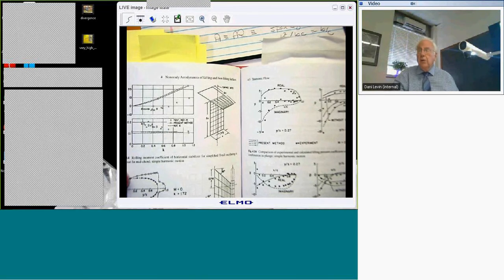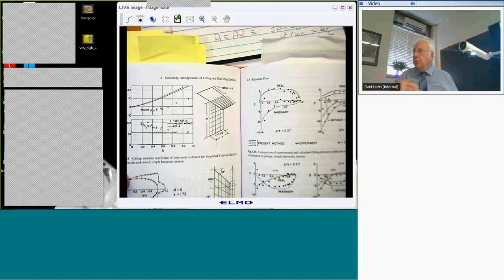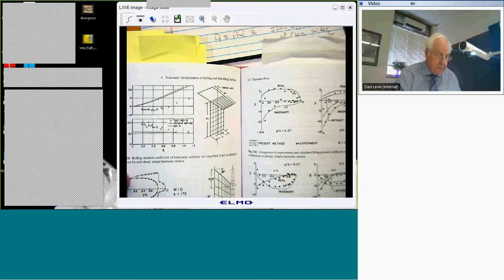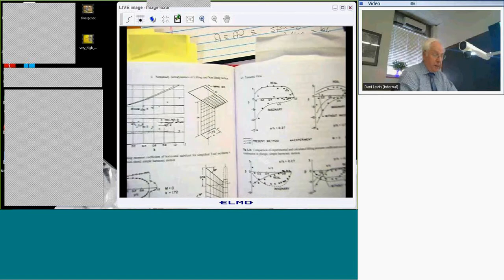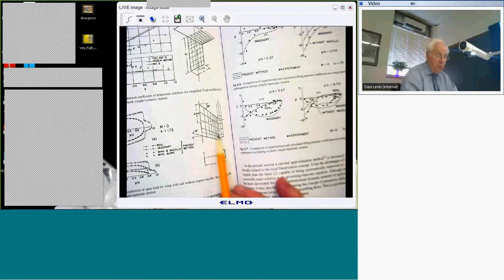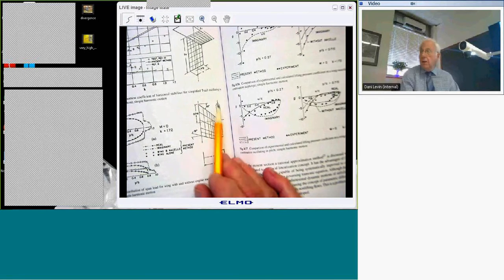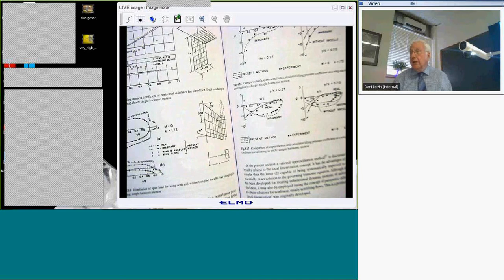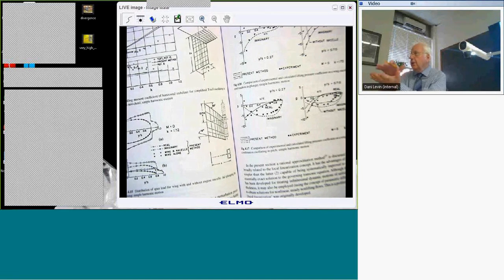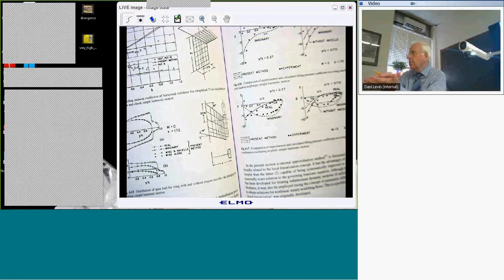Maybe they're prone to flutter because the theory is less reliable in predicting flutter, and therefore you're more likely to encounter it because your mathematical model isn't as good and things will happen that you don't expect. People have also done calculations where you have a wing and then you put a missile on the end of it. Although typically in the code, they squash the missile to a flat plate, right? Which is a fairly severe approximation.